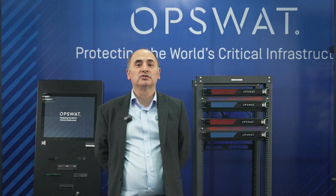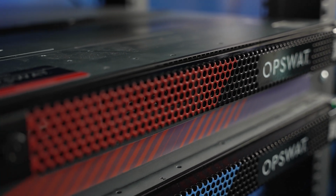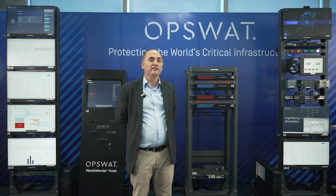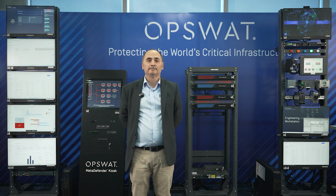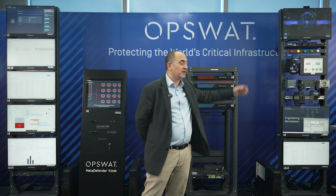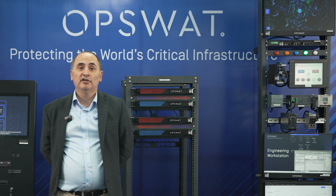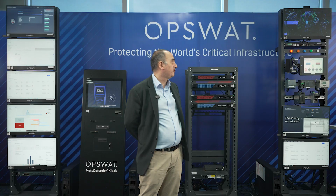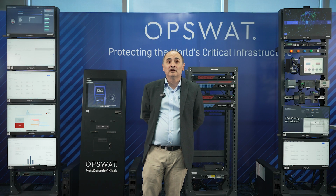The second method is to create an air gap, which ensures data can only pass in one direction. And this is achieved by the NetWall. You can either do this by the unidirectional gateway or with the hardware enforcement using the network data diode with the optical separation. This allows data to go from OT to IT, but critically it protects that key OT infrastructure. If you use the optical diode, it's actually physically impossible to go from this side back to the OT side.